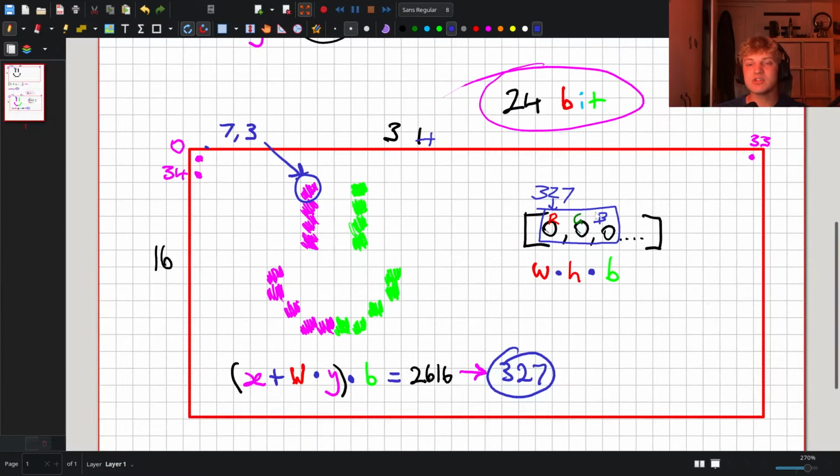So that is a very simple overview of the concept of a frame buffer, how you might store one in memory, and bit depth. While we're on the subject of frames and frame buffers, I want to talk about refresh rate and frame rate. Now, these are very popular terms with gamers, of course, because these two things as a sort of coupled pair determine how smooth or fluid any animations, graphics, video playback look to the person experiencing them. Now, refresh rate, you can think of it as the hard cap, and this is measured in hertz. In terms of frame buffers, this is the number of times per second that we can push a frame buffer update to the display.